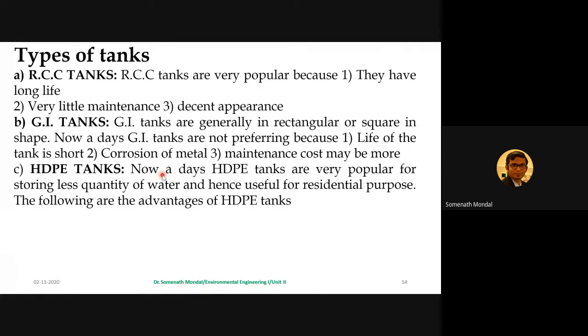So in our country, the philosophy is, since we have a deficit in competent manpower, that is the reason we don't prefer structures which need more maintenance. So that is the reason RCC tanks are preferred these days.